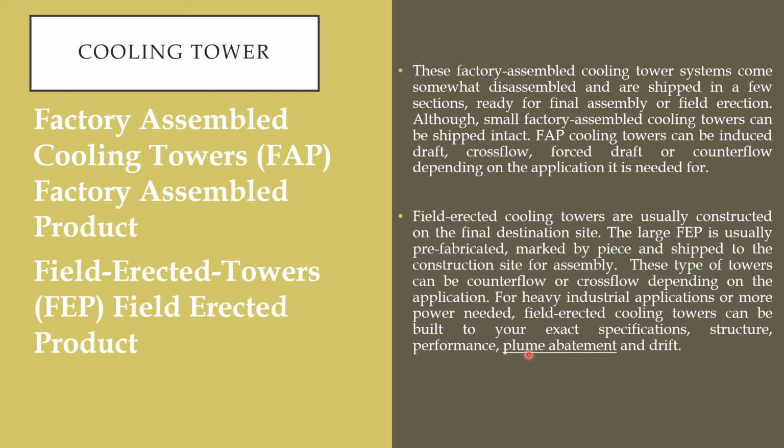Plume abatement, that is the water vapor cloud formed during the winter season or cold season, can be avoided, and drift as well. Field erected cooling towers or crossflow cooling towers are normally used in our country. Open type cooling towers are the field erected type cooling tower only.